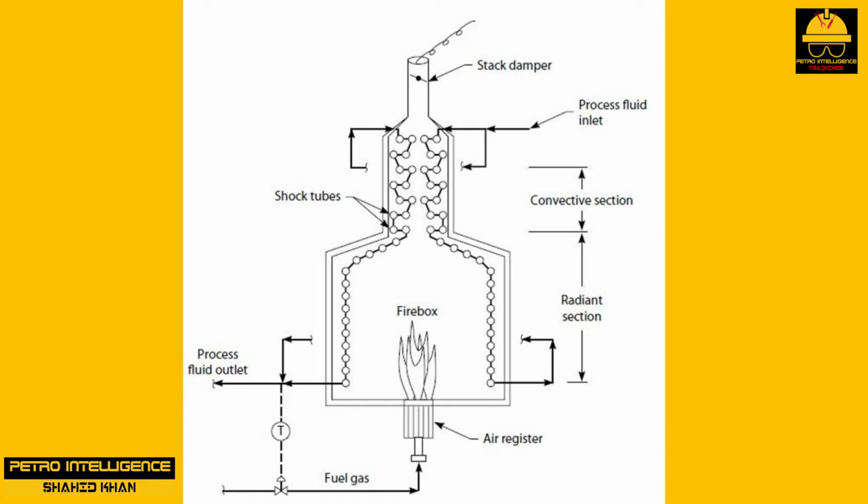This usually results in afterburn in the convective section or stack and can even lead to explosive detonations. The products of partial combustion are atmospheric pollutants. It is not possible to operate an automatic temperature control on the wrong side of the point of absolute combustion.